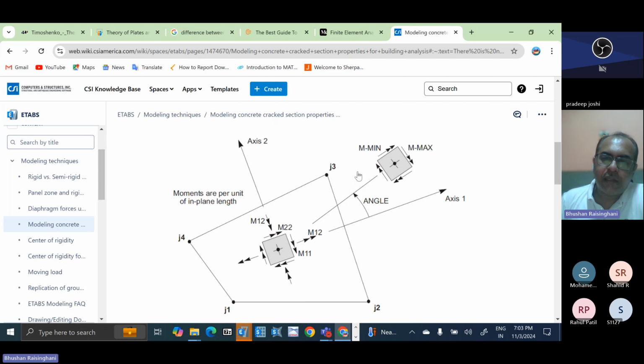So that's why there is this angle theta. If it is having some angle with respect to your some system, that particular column has its own xyz, and the full building has its own xyz. So building xyz, column xyz, both are different. The xyz of the slab and the building may be separate, but at element level, it is at member only. It is the xyz of the particular member. They may be with a global system or not, but your definition is in the local system, which may be the same as the global system or may not be the same. Your definition is always in the local system, x, y, z.